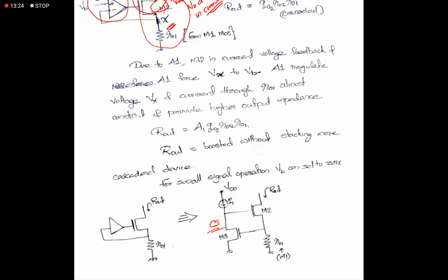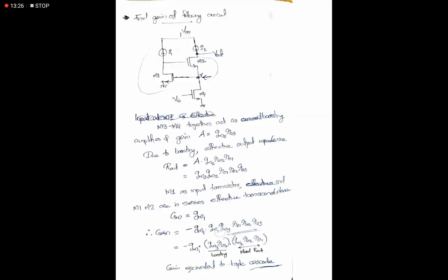So for example, in this case, to find the gain of the following circuit, you can note that at node X an amplifier stage is connected to M2, so this will act as a cascaded configuration with the amplifier, which will improve the output resistance.